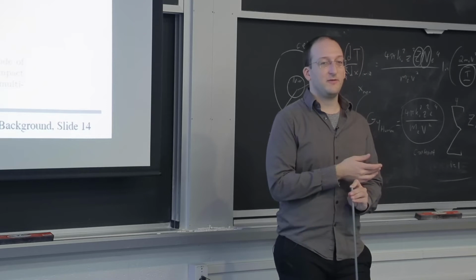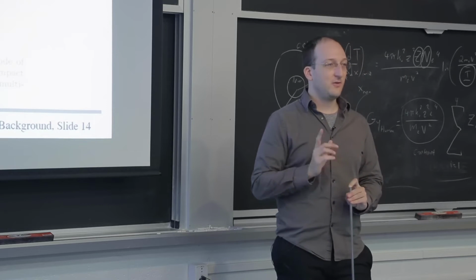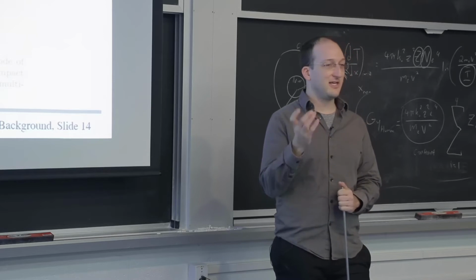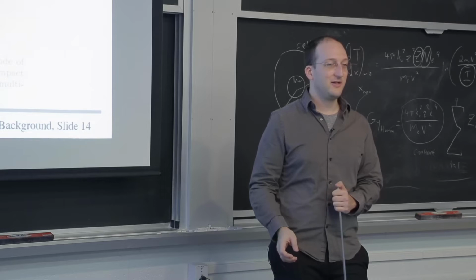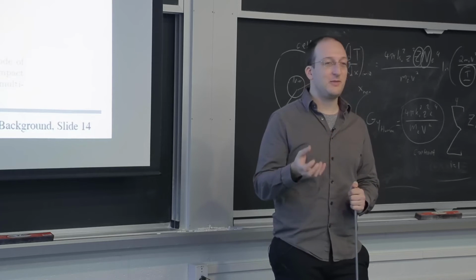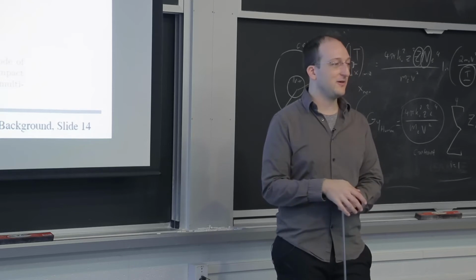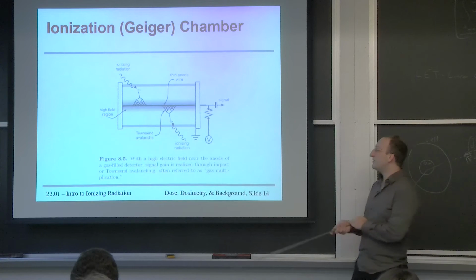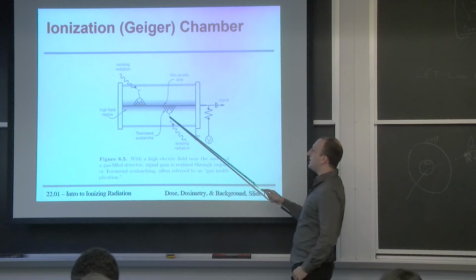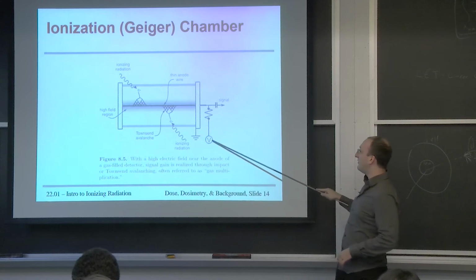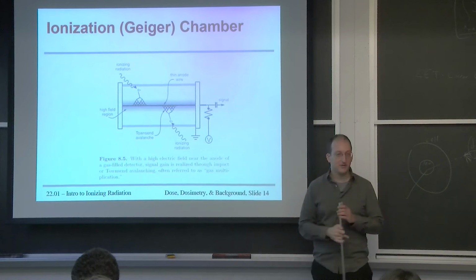Those old Soviet SBM-20 tubes have actually survived being stepped on and crushed. As long as the electrodes don't short out, they still work. There are a few folks in the department that have clearly bent Geiger tubes. One of them looks like it's been chewed, but they still work. Because anything interacting with the gas will cause an ionization cascade, which is immediately sucked into the electrodes by a high voltage and collected as a current pulse.